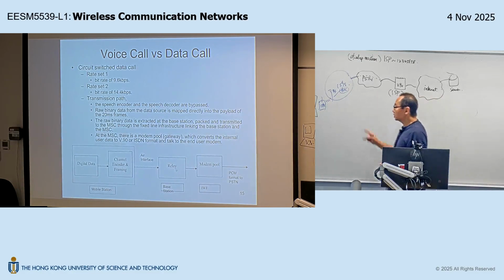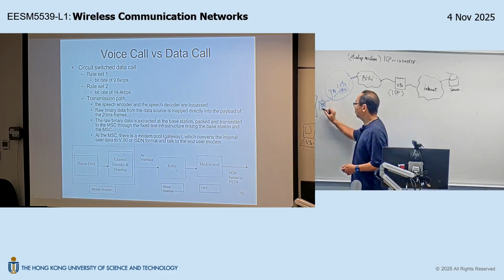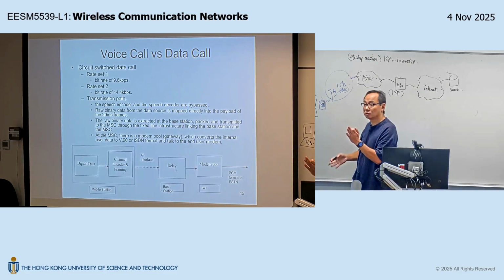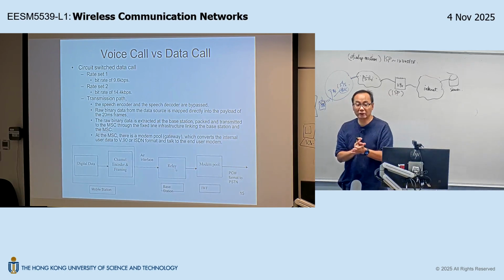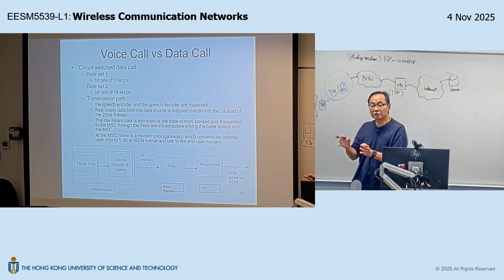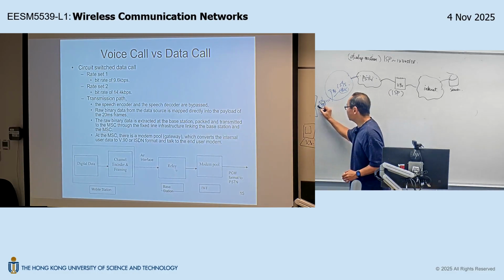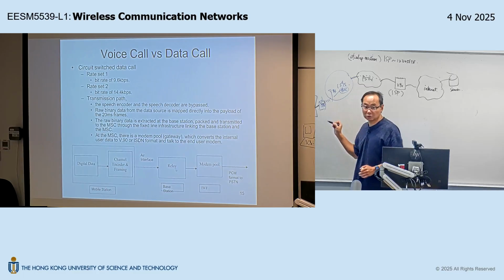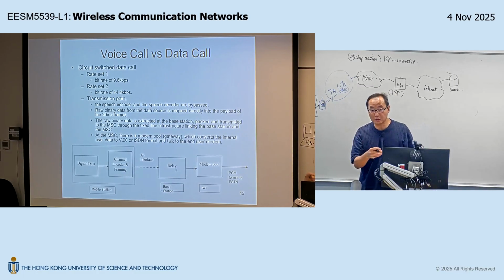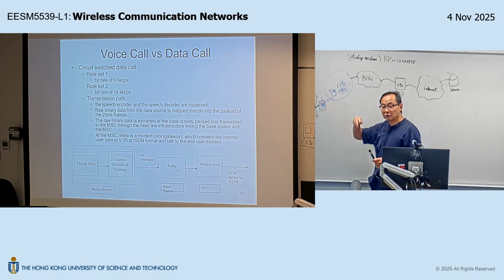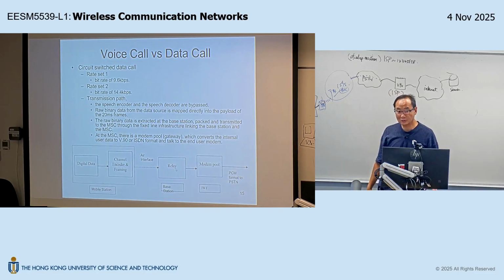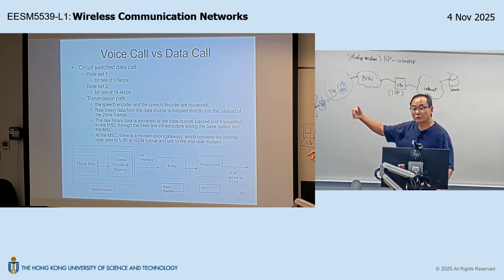When you access internet, at that time, the mobile station have on the side of the mobile station, they have something called infrared port. Now, of course, nobody is using infrared anymore. You just think of infrared as now the modern days Bluetooth, okay? So through this infrared, you connect, it's a COM connection. You connect to a serial port of the laptop. So in other words, the laptop will see your mobile as a COM device, okay? Let's say it's connected through Bluetooth to your COM1.